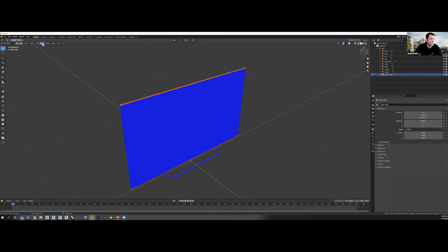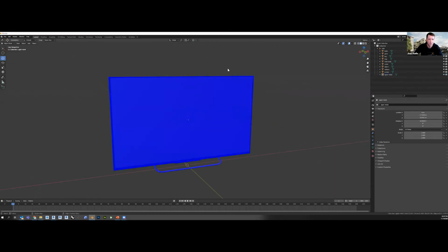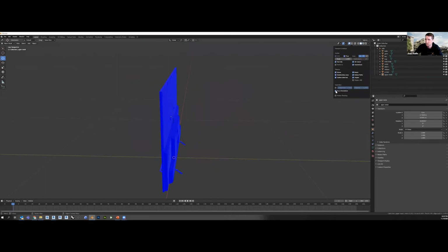If I go to mesh and I go to normals, because these are face normals on your 3D geometry. So if I just hit flip, because that's what happened, just the normals are flipped. So we're going to simply flip them and they're going to display correctly now. And we can see here, that's fixed. Perfect. That's what we want. So now I'm going to go back to object, and I will turn this off here.